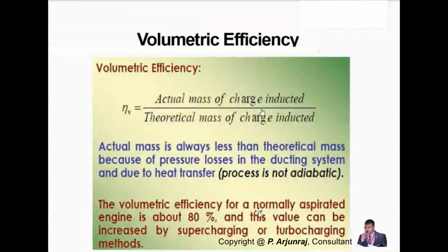And if you're going for a naturally aspirated engine, which means without turbocharger, we have seen the volumetric efficiency is 80%, and the volumetric efficiency gets increased to 95 to 98% when you're going for supercharging or turbocharging methods.